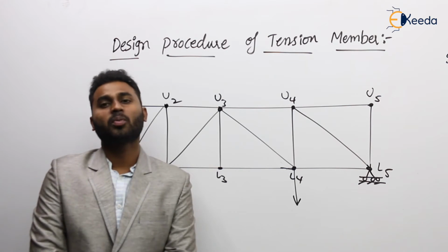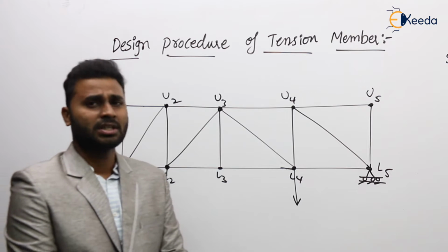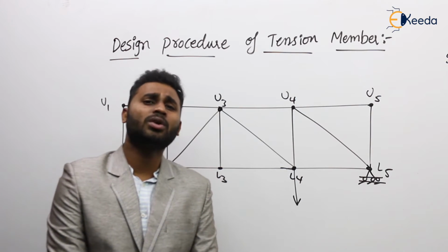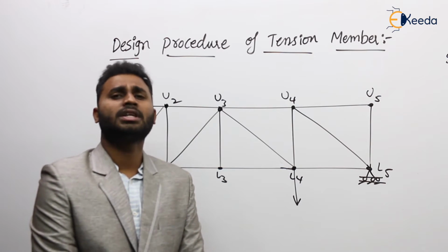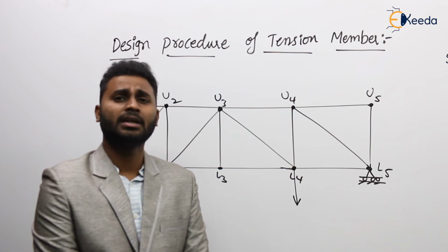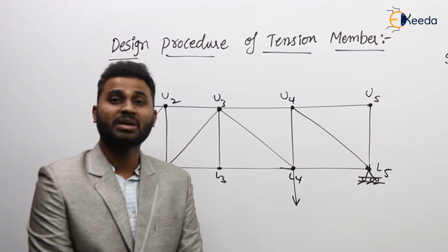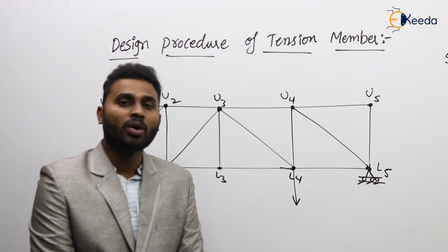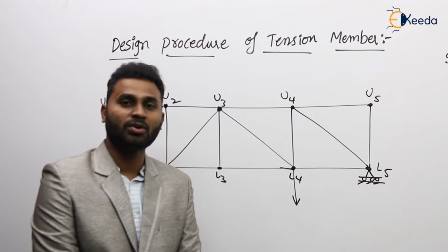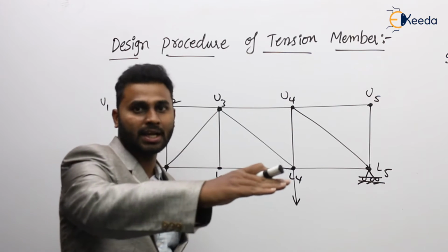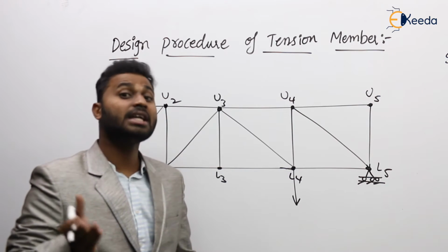And one more point here. If we take a bridge truss, what is the major load? Okay, so a bridge truss is subjected to which type of loads? Mainly, tell me. A bridge truss is subjected to live load, which you can also call imposed load. Live load or imposed load means the moving train mainly. Okay, that is a live load. And then its self-weight itself.